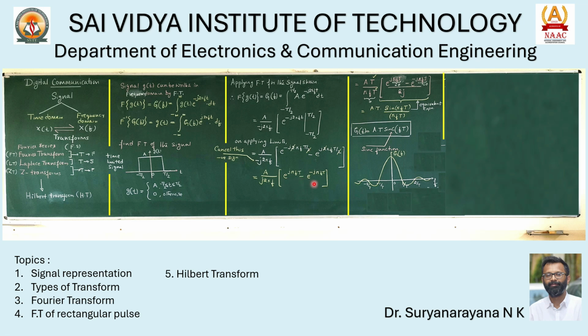Here we have to observe that this exponential expression is in the form of the trigonometric formula, that is e to the power of j theta. Therefore here we have to write this relation to obtain the sinc function. So I have here pi fT.